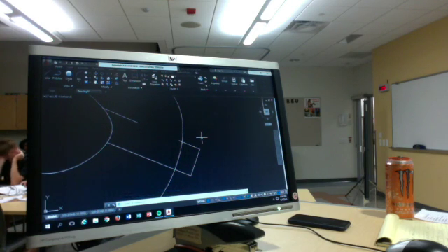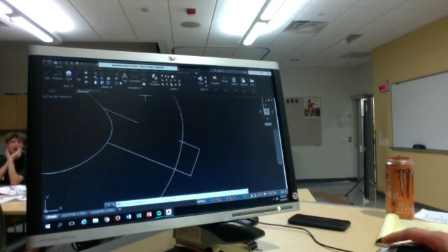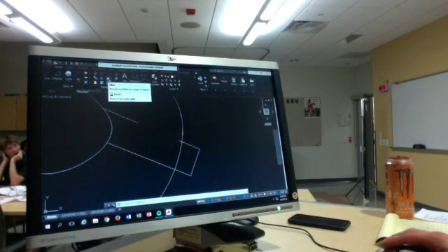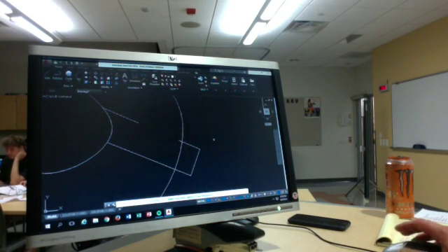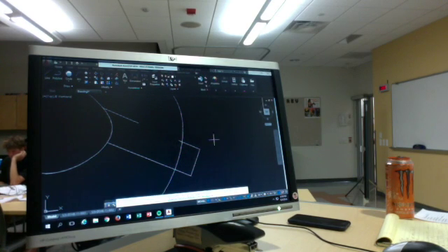We have the chamfer and fillet commands. Sometimes in a corner you want a chamfer or a fillet. Chamfer and fillet are so similar that they are under the same command up here. If you choose fillet, there are different things that you can do in here. One of the first ones is choosing your radius. The radius is how big the fillet actually is. So you can make it 0.25.